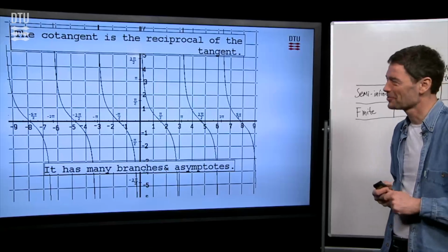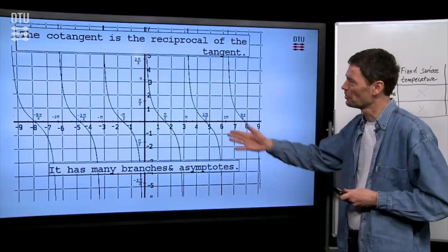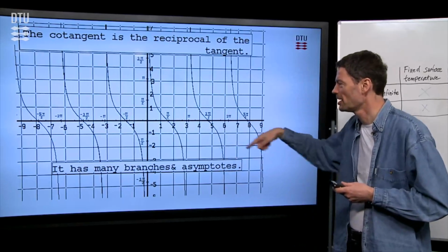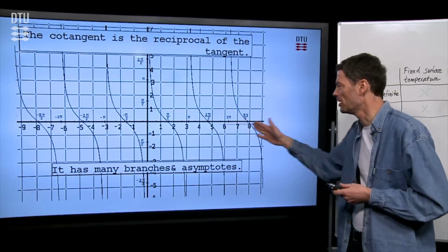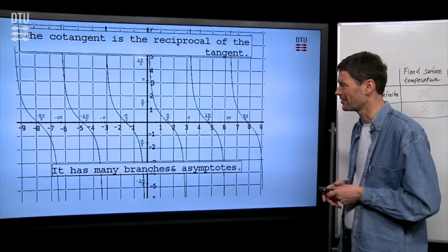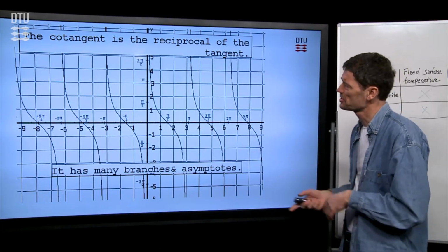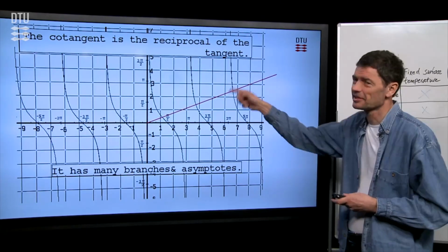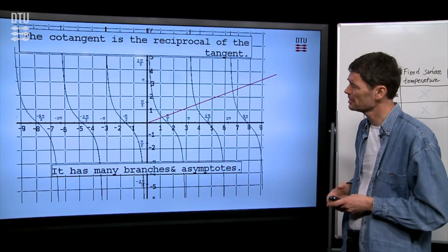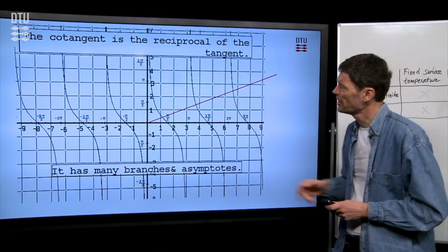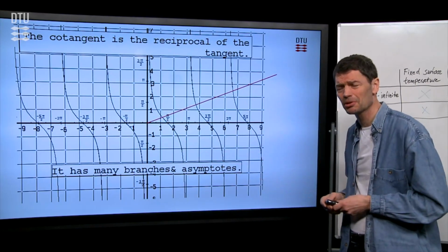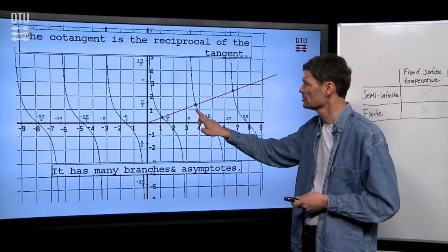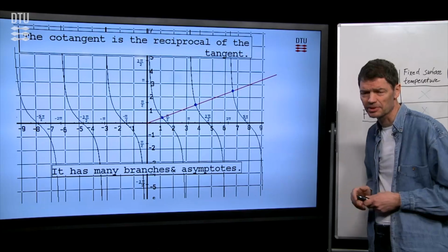This is a little bit old graphics which I've copied. We show a plot of the cotangent function, a repetitive function that comes again and again for every pi we go out on the abscissa axis. That should be equal to that line, zeta divided by Bi, as I had on the previous slide. And where they have intersection points, that is where we have the so-called roots. So the roots are here: zeta 1, zeta 2, zeta 3, and you can expand and find the next ones also.